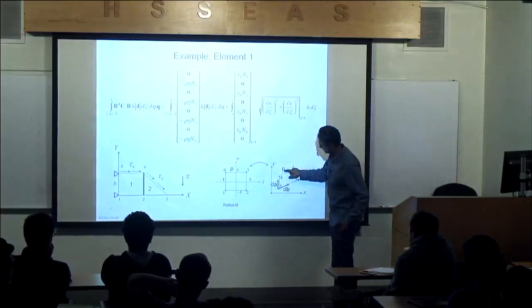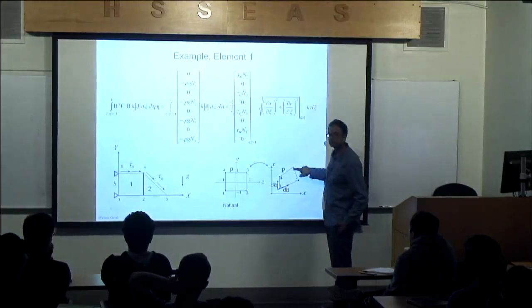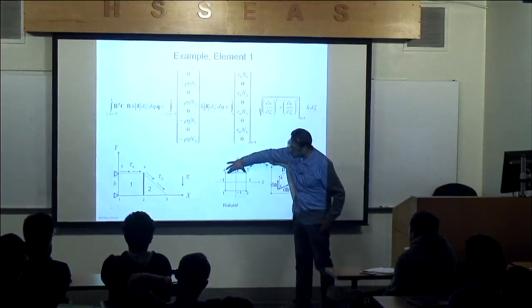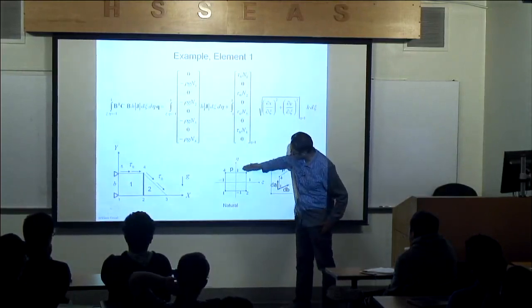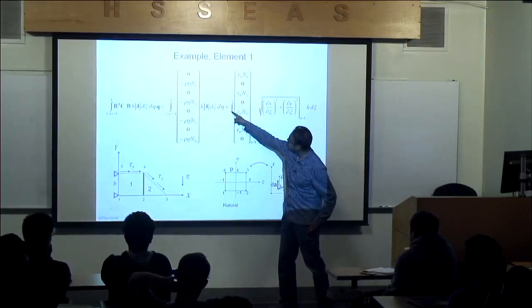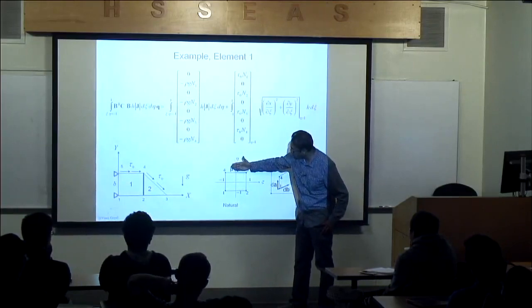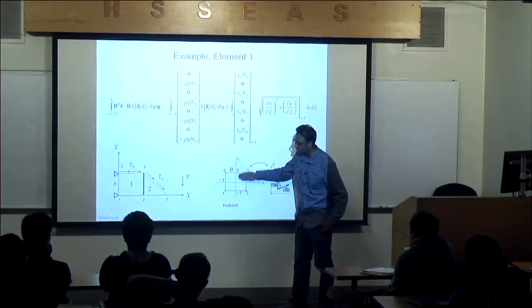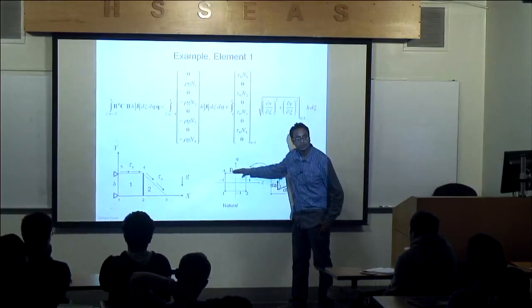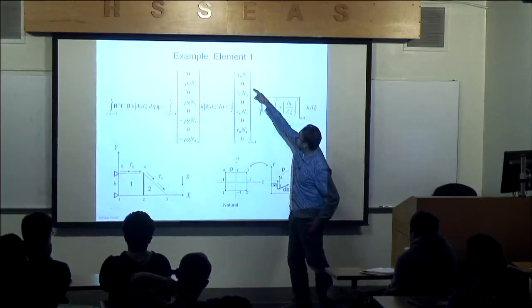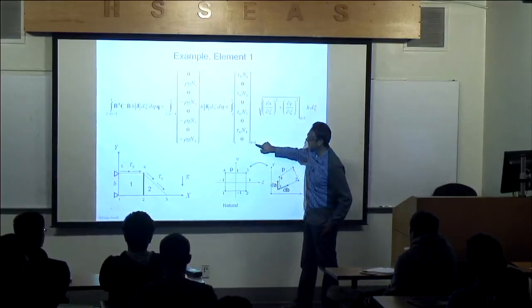And when I do that, that piece really acting on this connectivity, this edge, 3, 4, maps into this edge, which is 3, 4. And so I have to evaluate this integral along this edge. You agree? Yeah? Don't you agree that this edge is given by eta equals 1? Right? So I have to evaluate this shape function matrix at eta equals 1.